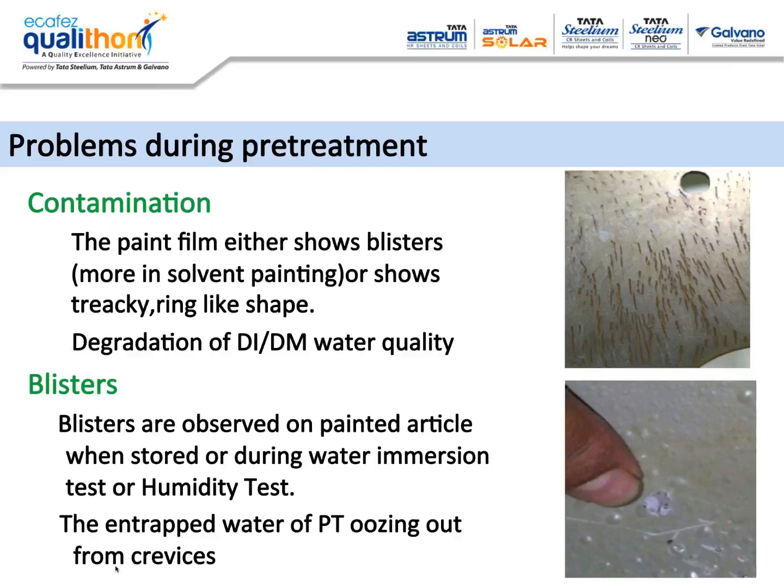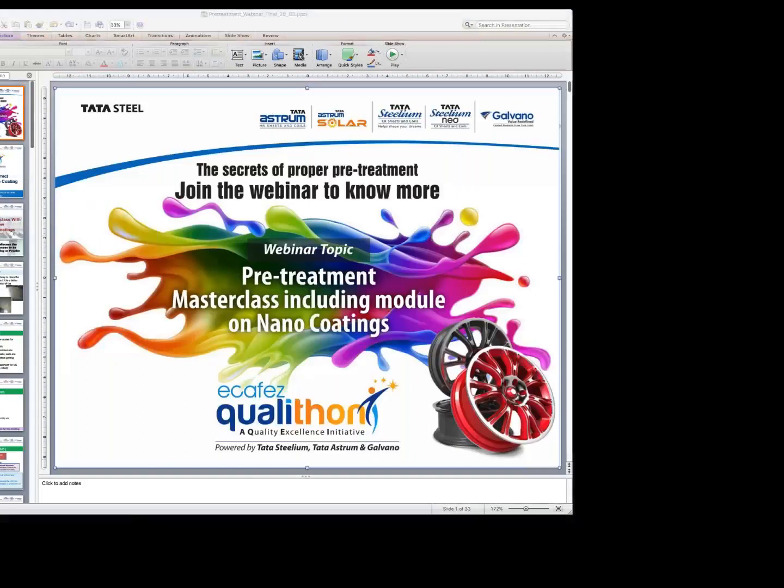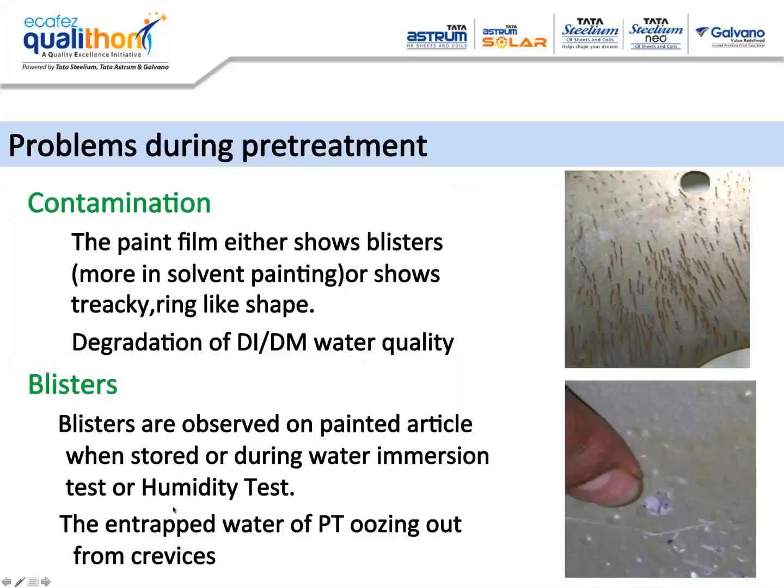After that stage, they will become salt water, and if there is salt water underneath the film, the osmosis will start, and it will start pulling the humidity faster, and at that point the paint film will blow.